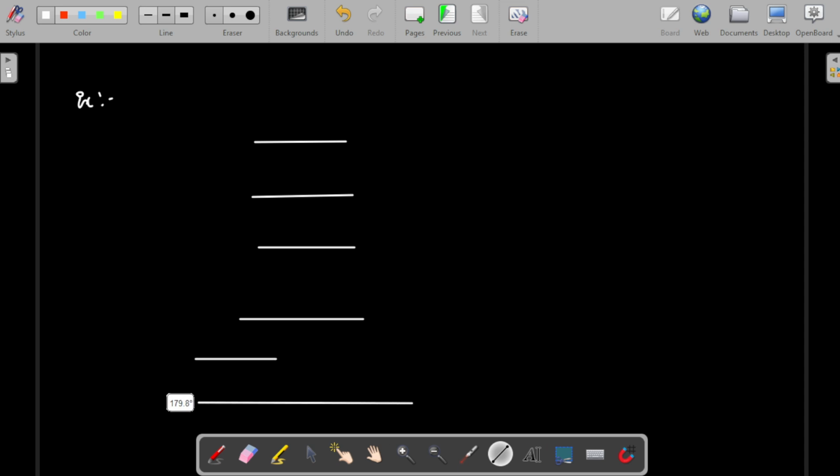So this is drift. Let me give arrow marks. This is diffusion, the diffusion of something like electrons, holes, anything. Because of that, some internal electric field will be building. This is the internal electric field that will be building. Because of the internal electric field, there will be drift. We are taking this for p-type, so the electric field and the drift are happening in the same direction. If it is electron, then it will be in the opposite direction.